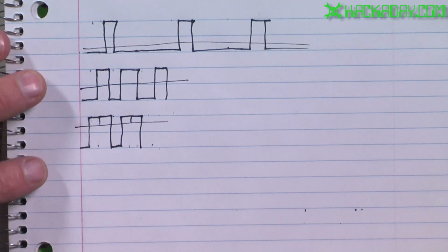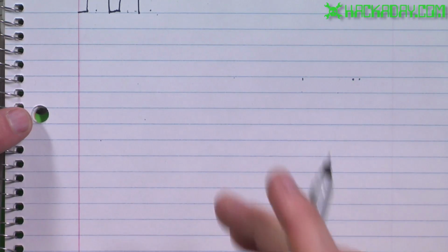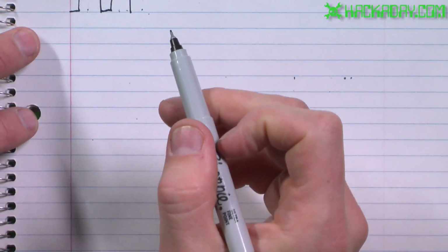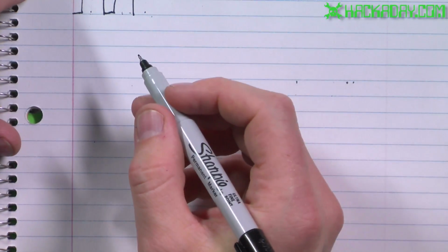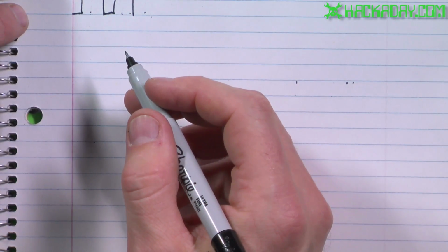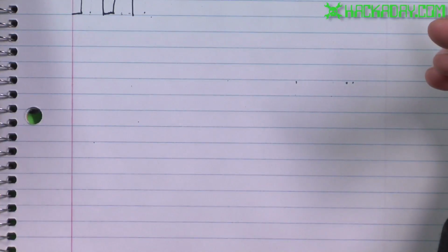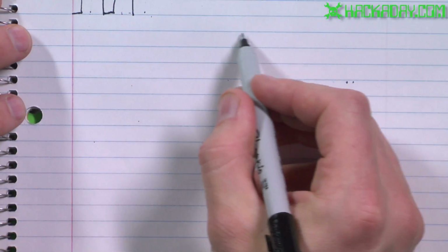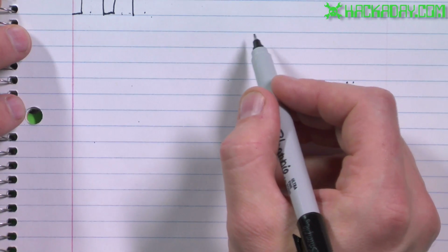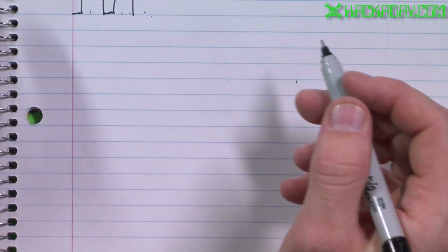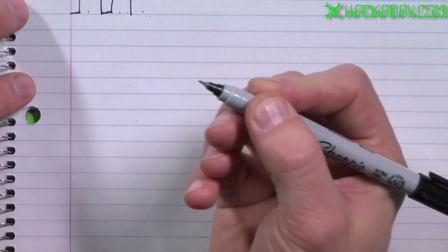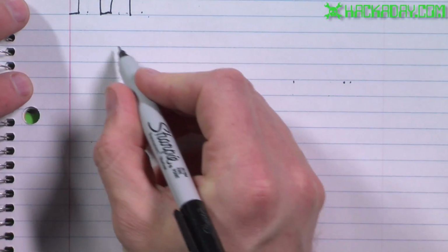That's another strategy. One final one that I'm going to show you is, actually I have no idea what it's called, but this one's very useful if you are using interrupts to control your pulse width modulation, and you don't want to have it happen every cycle. If you have a bit depth of 8 bits for your pulse width modulation, you don't necessarily want your interrupt to happen 256 times per cycle. That'll just suck up your processor power like crazy. So if you don't have hardware for pulse width modulation, here's one thing that you can do.